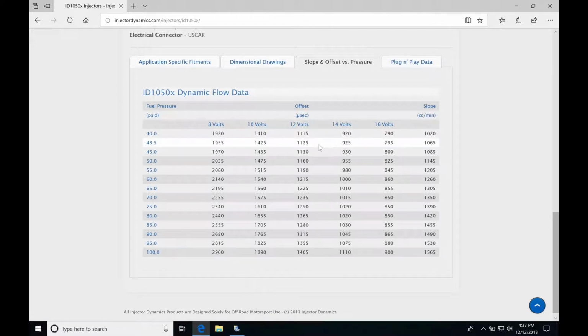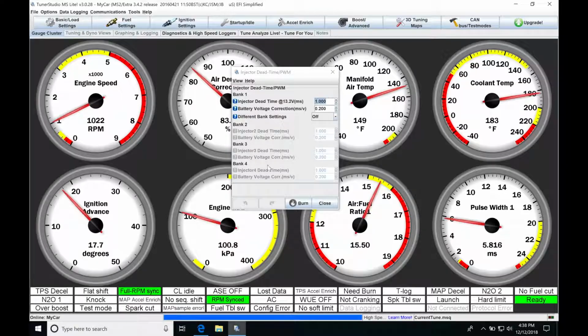So if I'm looking at the data point between these that we don't have, it's going to be roughly 1,025 microseconds, roughly. So we would go in here to our table and we would type in 1.025. This is in milliseconds, those are in microseconds. It's just the difference of our units. We have to shift our decimal place over 3 to the left. That's why we get 1.025.